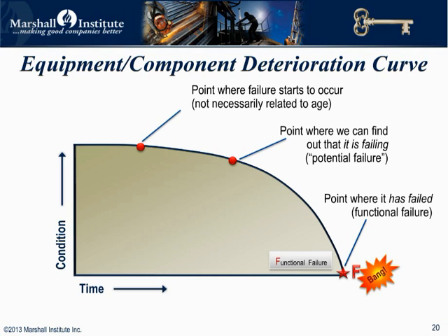Think about a bearing or drive belt. Wear is a kind of failure that occurs over a long period of time, essentially from the very beginning, but functional failure of the bearing, that is, when the bearing no longer facilitates rotation of the shaft it's on, doesn't occur for a long time. That can be months, maybe even years, over millions of cycles. Many times this deterioration, this physical drift, is progressively visible or measurable evidence that something is changing, which if left alone will inevitably lead to functional failure. Thus what we have is called the P to F curve.